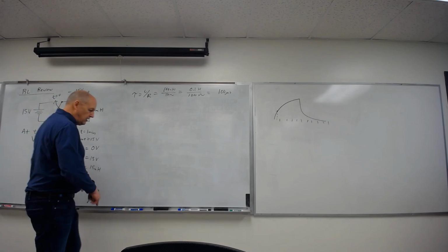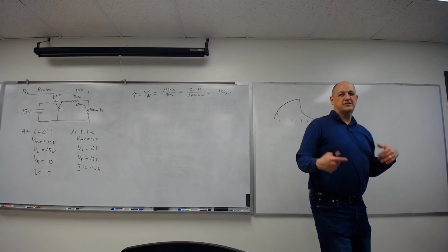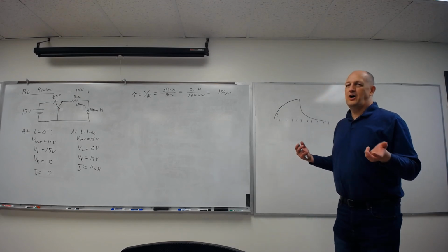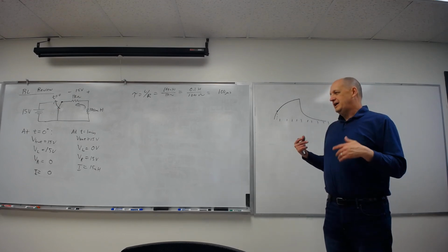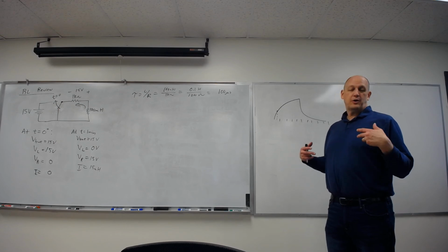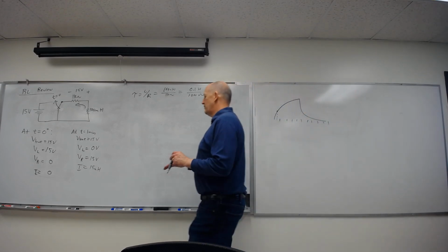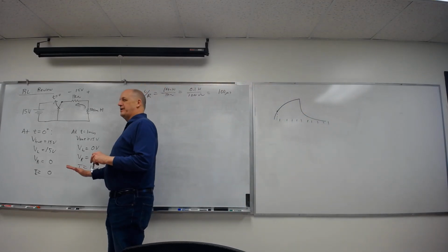When they're sitting there working and they're fully charged up, inductors are just like a short circuit. They're just like a wire. And all they're going to do is prevent instant changes in current. They're going to make it always take a while. It takes a while when you flip the switch for the current to ramp up. It'll take a while for it to ramp back down.